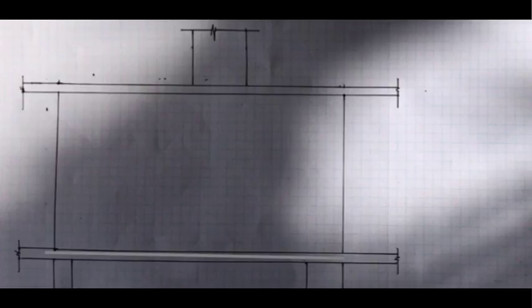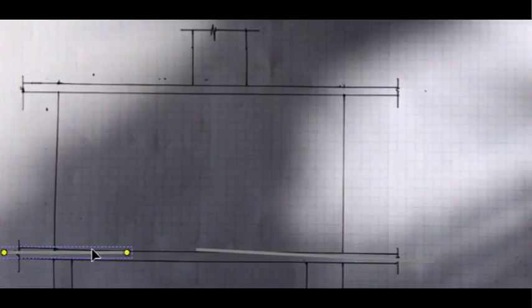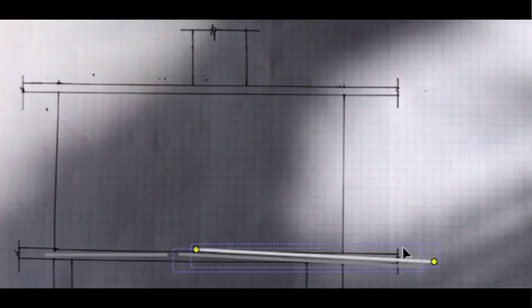For the strut and tie method, when the reinforcement is in tension, if we simply lap the bars together, something like this, then because this is in tension, it will just pull all the way out and it won't be effective. So what we need to install if reinforcement is in pure tension is something called mechanical couplers.